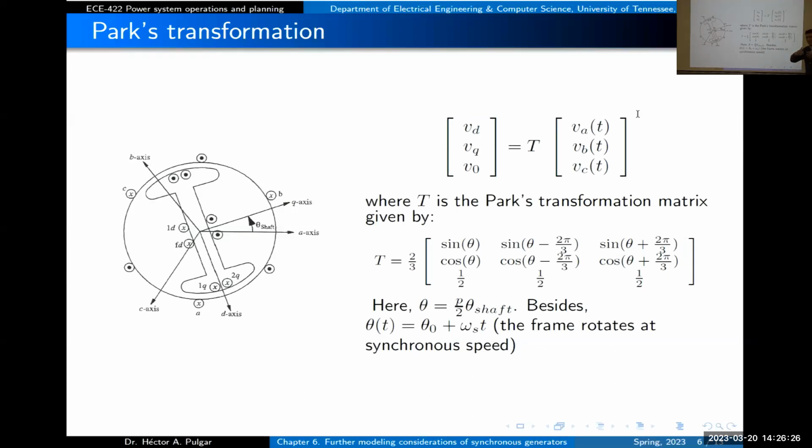What is the purpose of this dq0 transformation? So that we don't have to use sinusoidal time variance. Yeah. So the coefficient that we will have here changes in time. Inductance will change in time. And that can make things complicated.